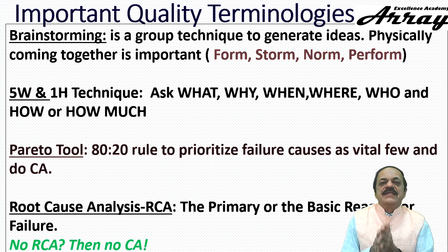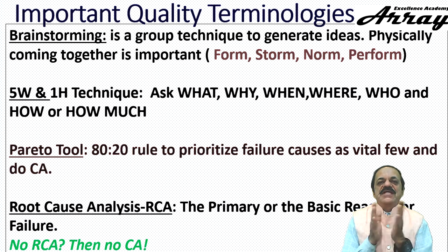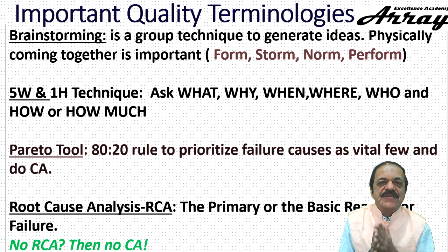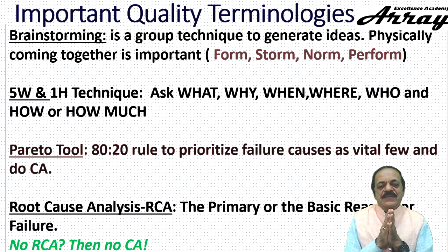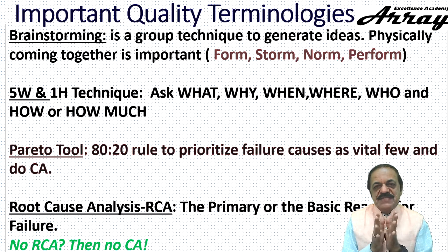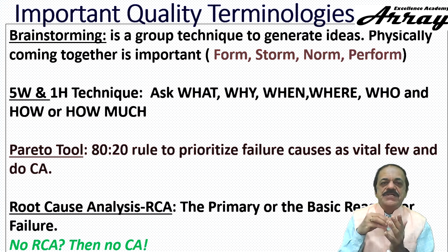Please remember, if you are not doing root cause analysis and you start doing the corrective action from your own experience or top-of-the-mind impression, that will never be a permanent improvement. So no RCA means no corrective action; corrective action should have root cause analysis before it is arrived at. This is a must. Please do not forget this.